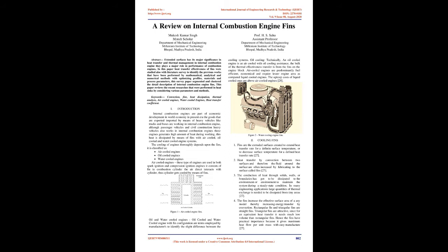2. Cooling fins. 1. Fins are the extended surfaces created to increase the heat transfer rate for a definite surface temperature, or to decrease the surface temperature for a defined heat transfer rate. 2. Heat transfer by convection between a surface and the fluid around the surface can be increased by fabricating extensions to the surface, called fins.